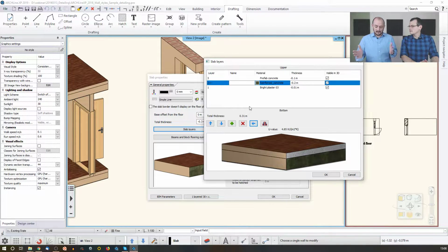Let's imagine you create a hole in this layer, but not in the rest. You can decide whether you would like to see that contour appearing on your floor plan or not, either by simply setting it up here, or by making other changes. But this is the best way to determine which layer contour is visible on the floor plan.